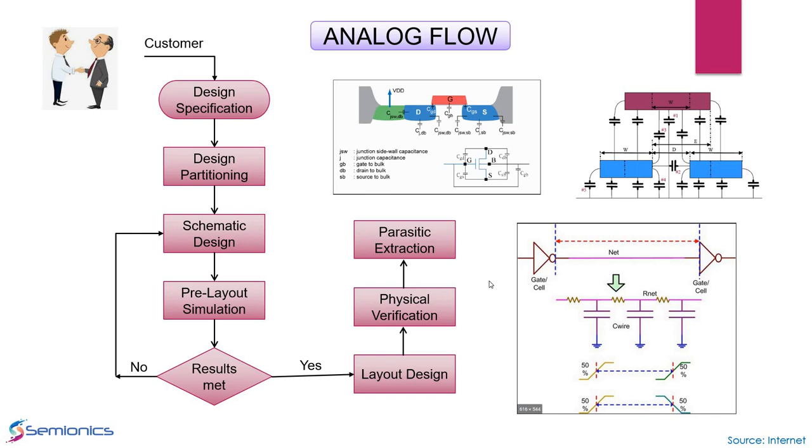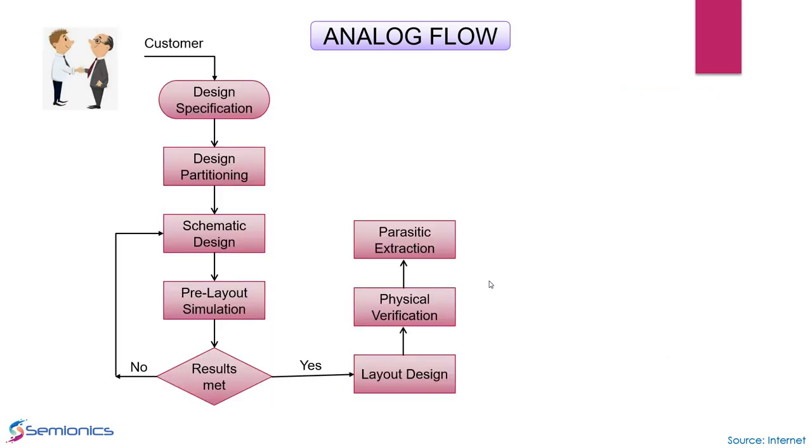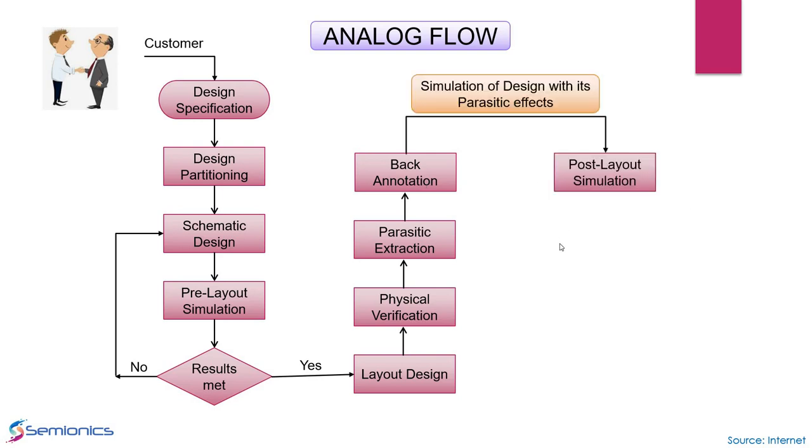So what do we do with this file? We back annotate it. Okay. The term used here is back annotation. So what is back annotation? Simulation of a design with its parasitic effects.